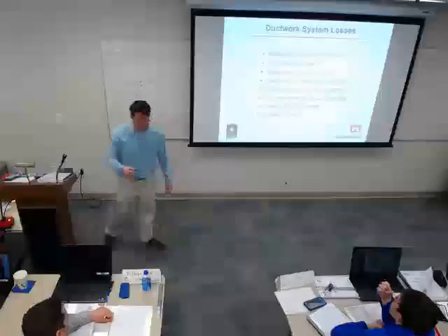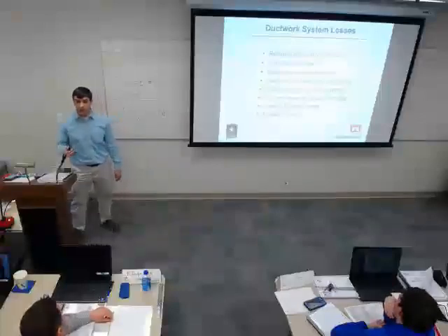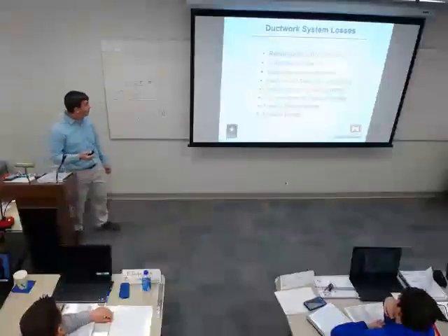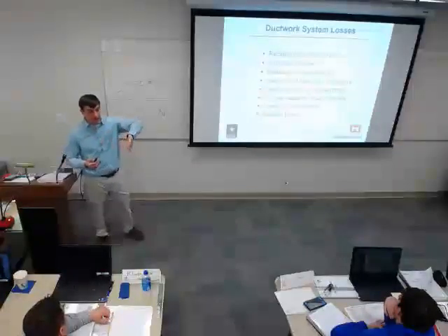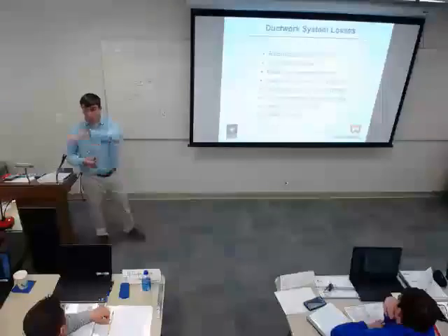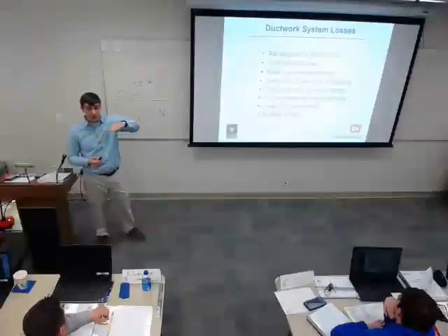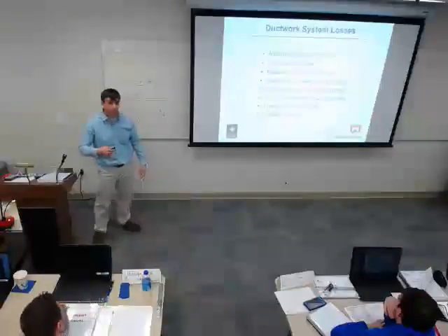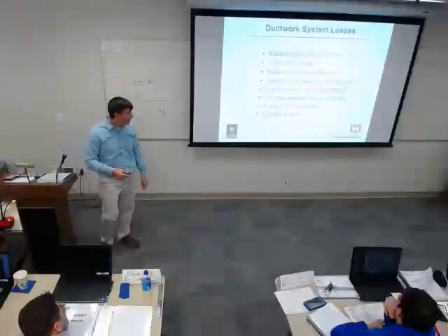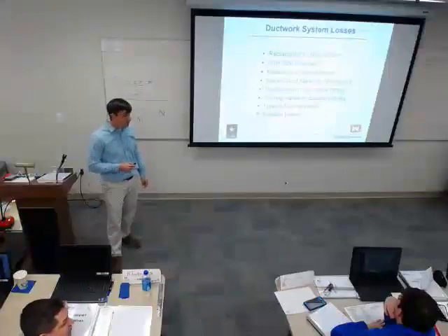Obstruction. Inevitably, I'm going to run into a piece of steel where my duct needs to be, and we've got smart ways that we can handle that. Four 90-degree fittings are more resistive than four 45-degree fittings. So if you run into the situation, let's try to be as smart as we can out in the field with whatever obstructions we're going to create.